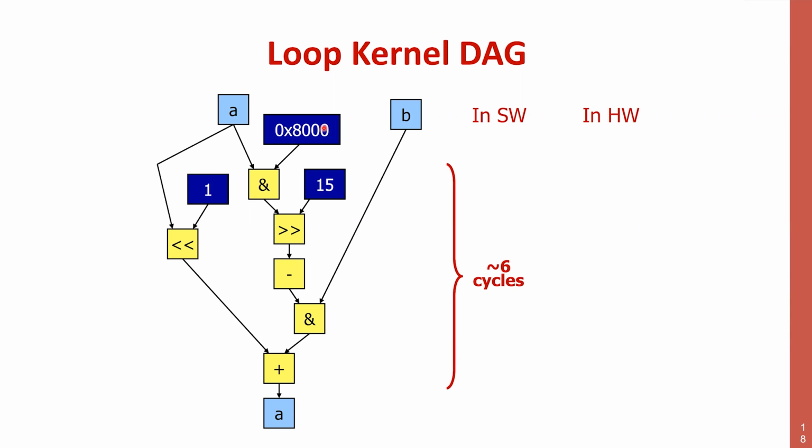Actually not. I need to take this bit, like bit number 0, for which this constant has a 0, and put it to the value 0, because it will always be 0, whatever the value of A. So for that bit, there is no transistor at all.